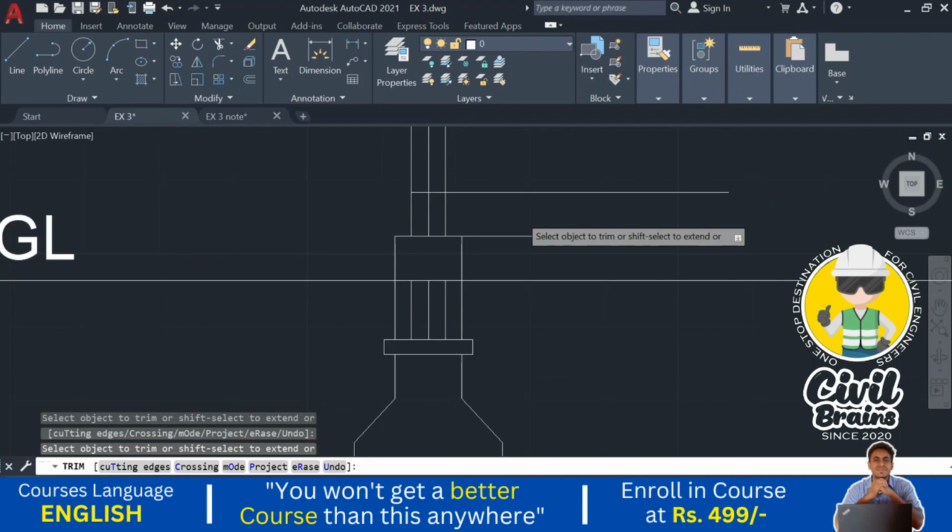Now I draw a section line here, a random section line over here. The same section line I take in the first floor also. Wherever you take the section line in the ground floor, the same place we need to take in the first floor also. Don't change that.